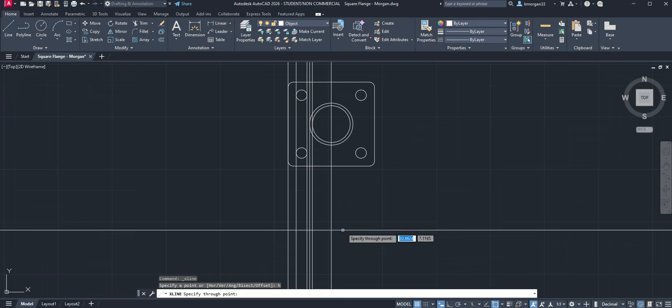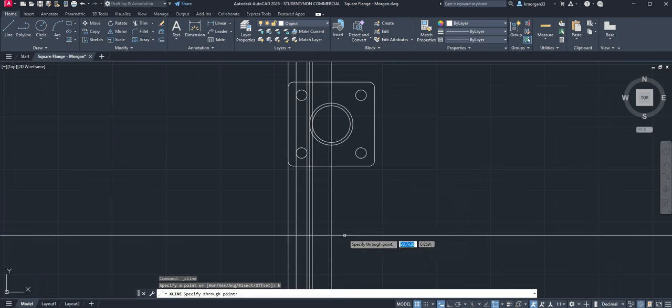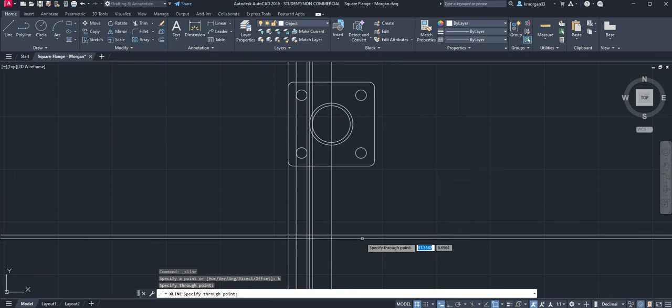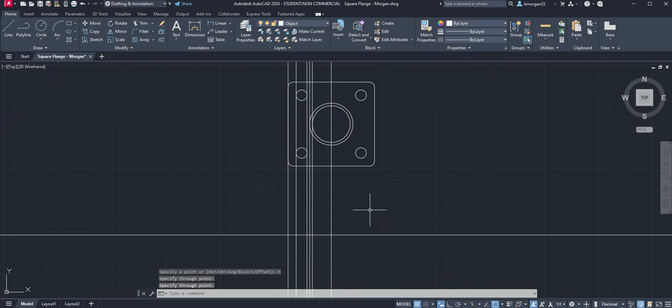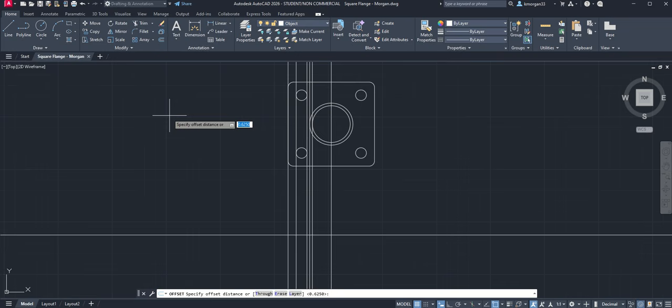So what you have to do is move it relatively around here, and then just click and place that line. See that? And then enter to confirm the line. And then let's go ahead and offset that line. Save it. All right, then we are going to offset. So let's click on the offset. We want to do about 2, I would say.